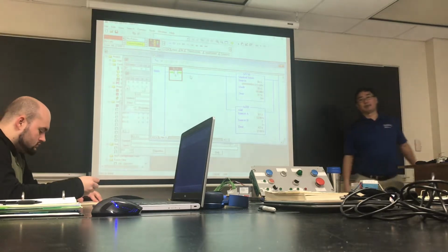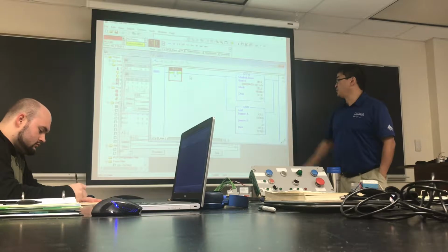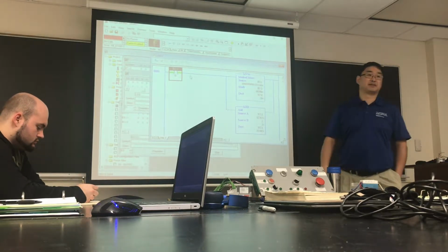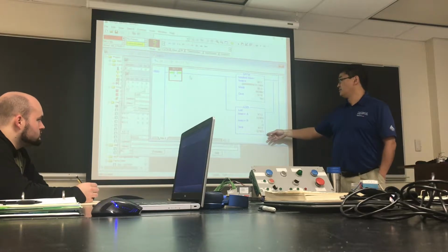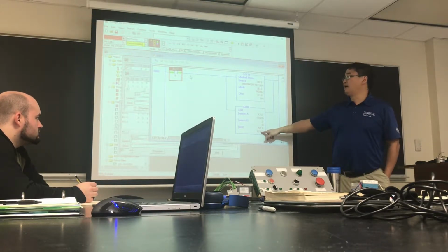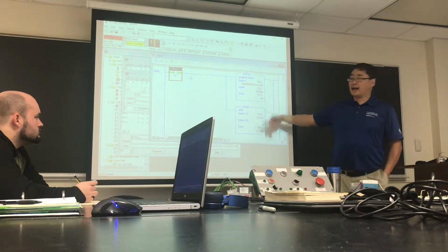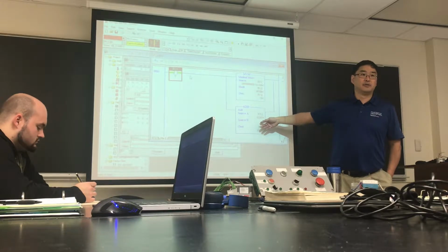And it just faulted out because I'd used a standard N7, which is a standard integer. So 32,767 is the max number I can stuff in there. And I think it might be 68, but either way, that's the max value I can fit in there. I sure as hell probably didn't want it to do that.